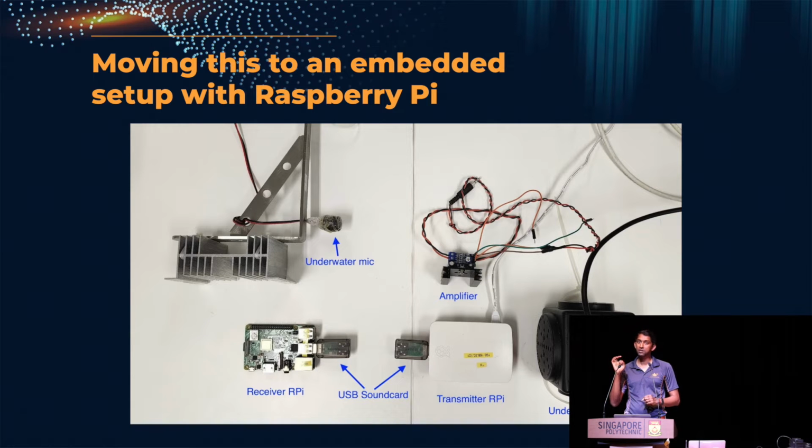Basically what you buy is just normal standard condenser mics or electret mics, put in a lot of hot glue, and then just connect it directly to the sound card. And it works for the kind of applications that we want to do in a pool. And in fact, that's what the mic is. In the blog, I have actually written on how we have made it. Feel free to experiment, and if you have better ways to make it, please do let us know. We'll be more than happy to publish it for you.